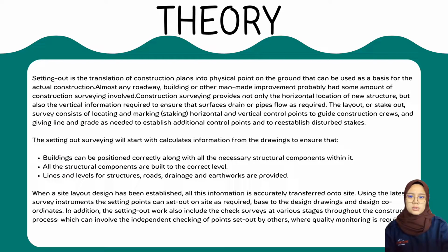The layout or stake-out survey consists of locating and marking horizontal and vertical control points to guide construction crews and giving lines and grade as needed to establish additional control points and to re-establish disturbed stakes. The setting out surveying will start with calculating information from drawings to ensure that, first, the building can be positioned correctly along with all the necessary structure components within it. The second one is all structure components are built to correct level, and third one is line or level for structures, road, drainage and earthworks are provided.